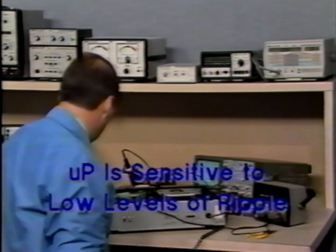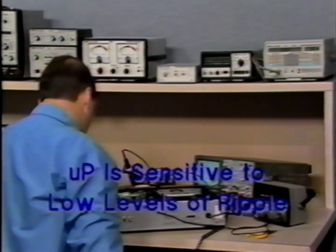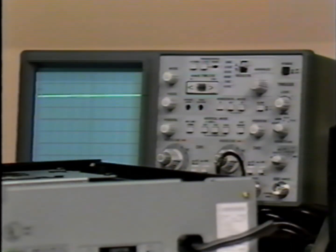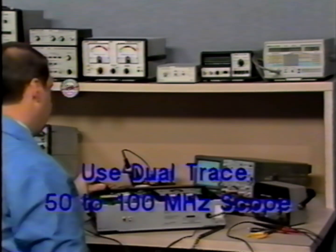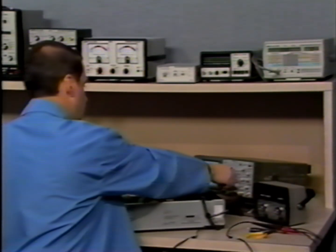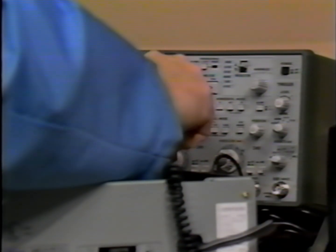Because the microprocessor is very sensitive to relatively low levels of power supply ripple, it's important to also measure the DC supply with an oscilloscope. The microprocessors used in consumer products can be tested with a dual trace 50 megahertz scope, but a 100 megahertz scope is recommended. So if you're currently repairing CDs or VCRs, the oscilloscope you are presently using will be adequate for the job.